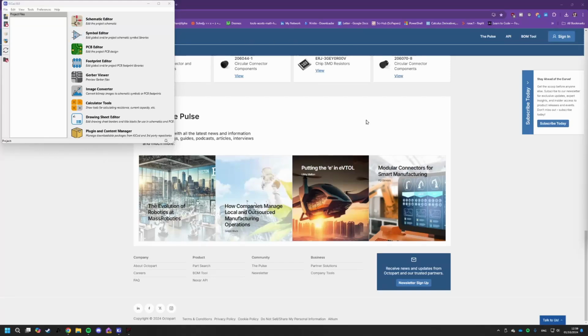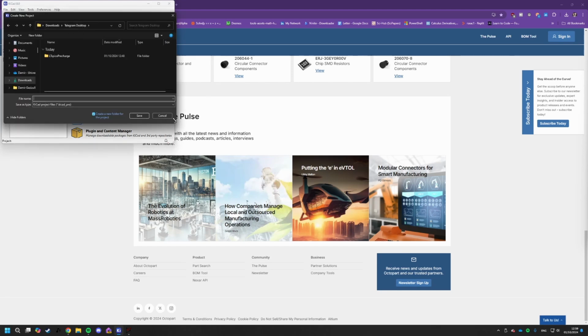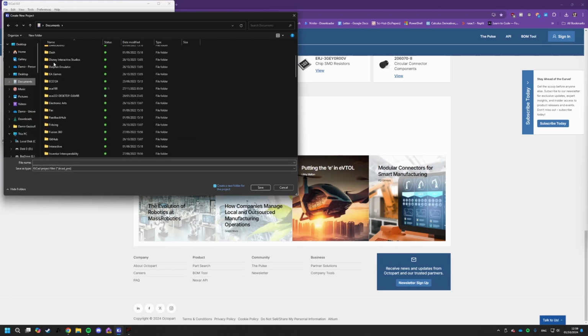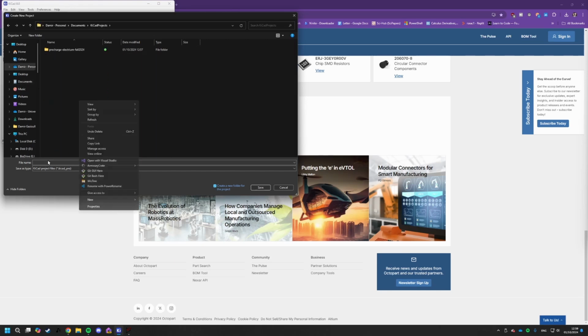Hey guys, this is the recording for the second electrical workshop in which we'll be making our schematic. So let's start off by creating our project. Just click new project and then probably make a folder on your computer. I made a folder in my documents folder under KiCad projects. Let's call this one Precharge. I cannot spell Precharge.